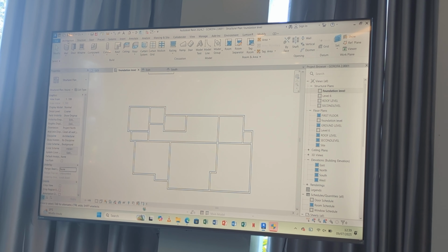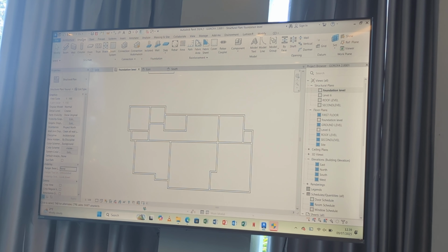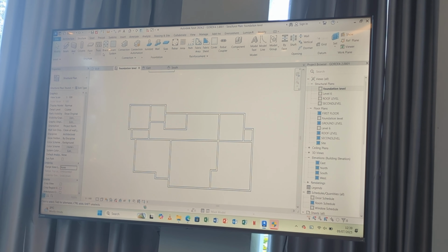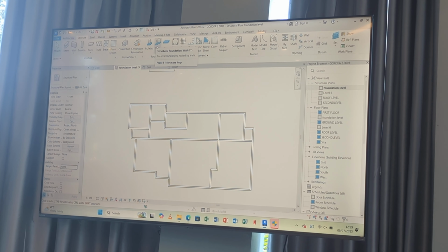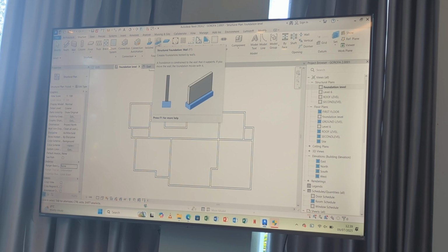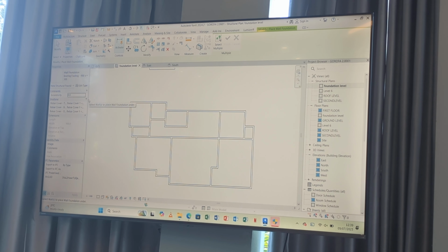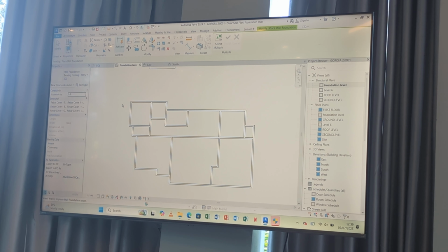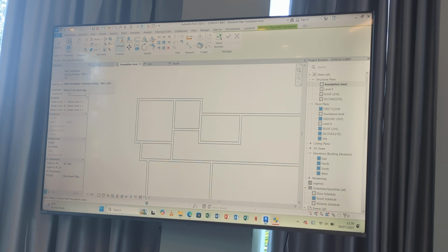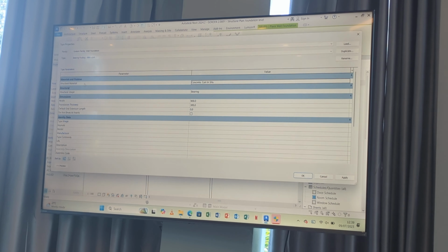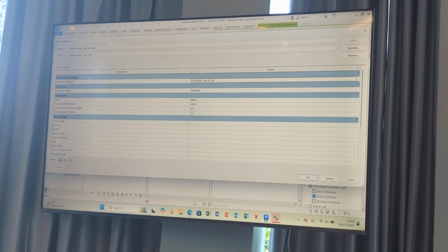You see past the architecture tab, go to the structure tab. Okay? Go to the structure tab. After the architecture tab, there is this wall. You see this, the structure foundation? That is just basically replacing a strip. Okay? So, there's this footing here. It has its size here. Edit it. We said it's 200 by 600.